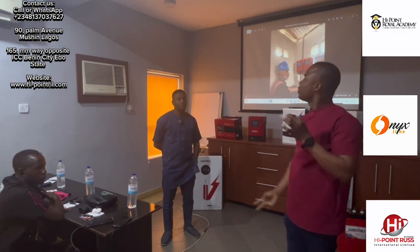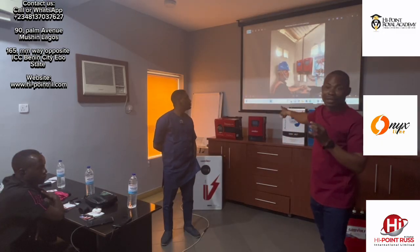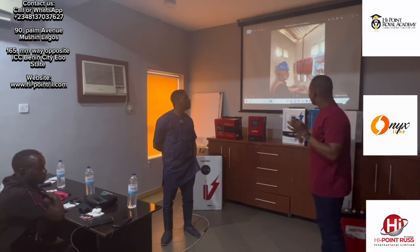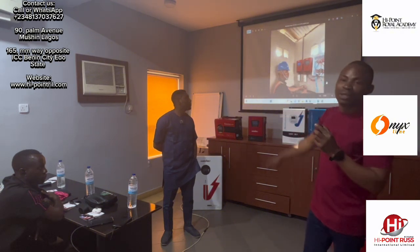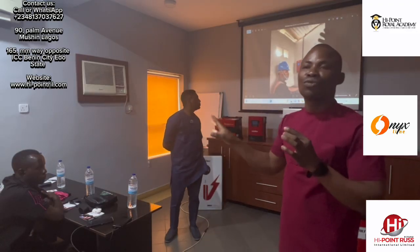After the series connections, the 2 strings go one to each charge controller. You can see 2 MC4 connectors there, and an MCCB DC breaker, with the panel wires. But the charge controller feeds back to the bus bar. So all the batteries are connected to the 2 charge controllers from the bus bar. Is that clear?